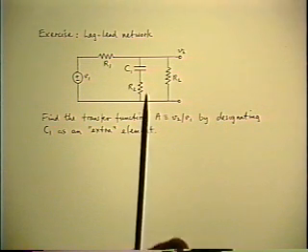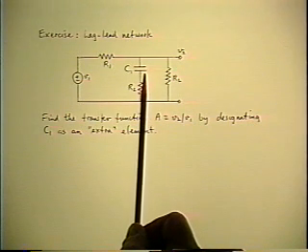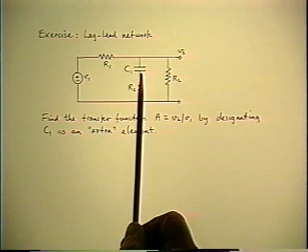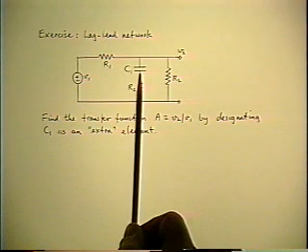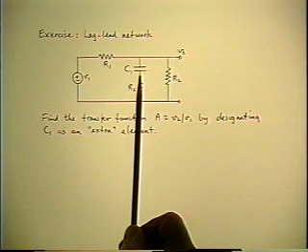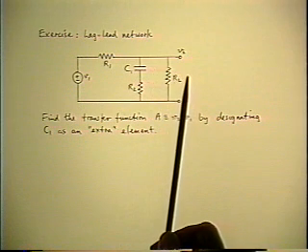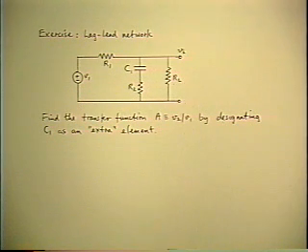Now what is the consequence of one choice versus the other? If you replace it with an open or with a short, what difference is there in the calculation? If you replace it with an open, the reference circuit is the same as the complete circuit at zero frequency, isn't it? So the reference gain will be the zero frequency gain, and that will come out front in the final answer.